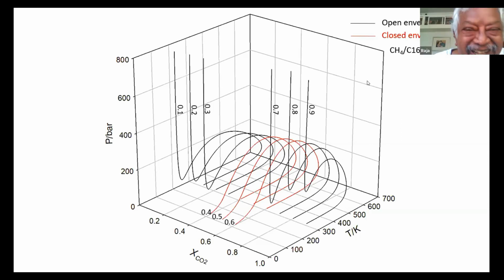It's a very nice presentation and very important observations you have made, but I just want to add that it's even true in the condensate fluids we are measuring. It does have two liquid phases, and regarding the classification you're talking about, a long time ago our friend Tavares in his master's thesis had in his appendix type 2, type 3. Now we find when you have many compounds, it's much more complex. You may have even type 8, and we find systems oscillate. That's the current system between 3 and 4.